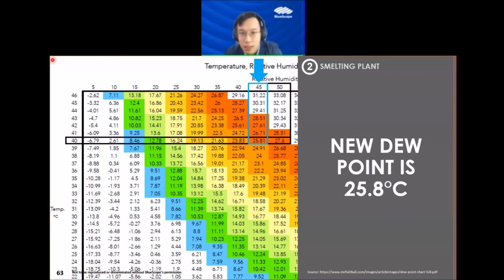Next one, I think from the same person, Ling: can I overpaint my roof if I find internal corrosion due to condensation? So if you saw there's rusting happening underneath the roof, whether painting it will solve the issue. My answer is yes and no, right?